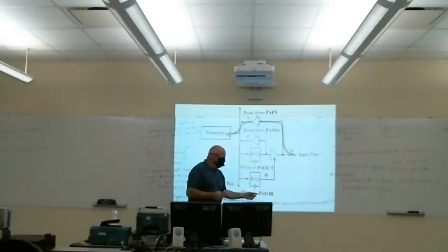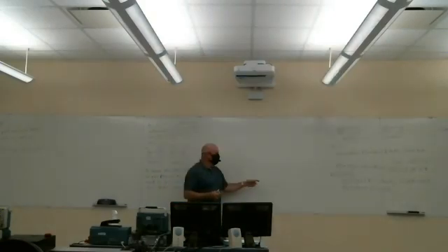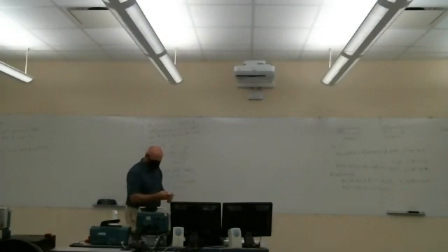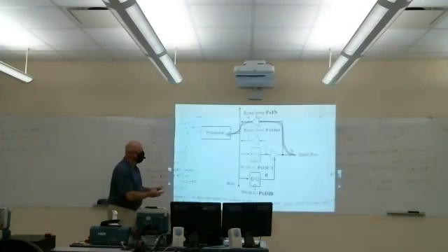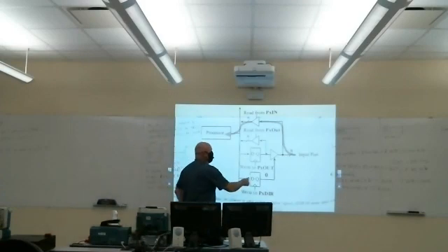But if you write a 0 to that bit in the P9 direction register, and it's set up for general purpose I/O, that means, whatever bit this is, let's say it's bit 3. So P9 bit 3, we've set it up as an input pin.